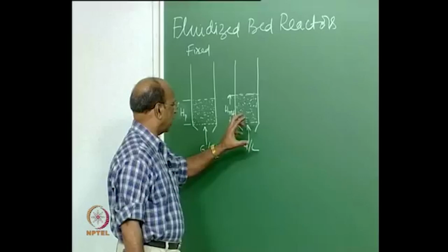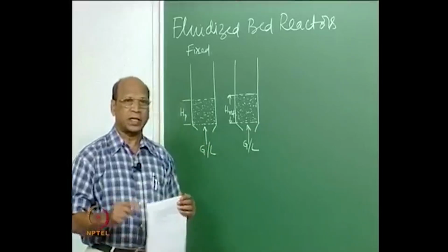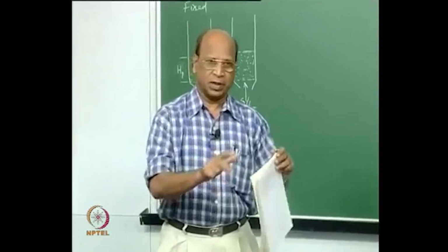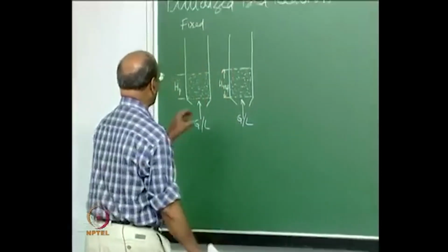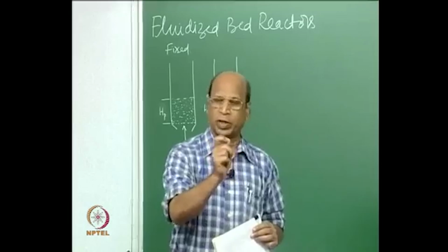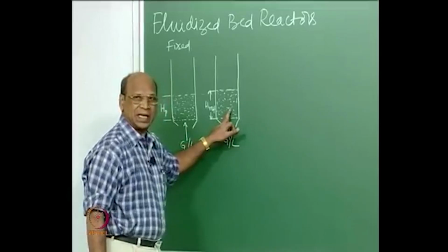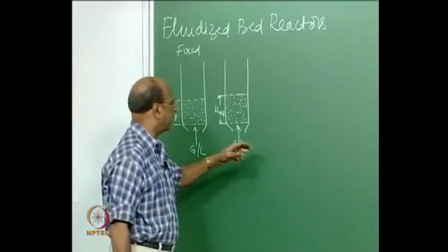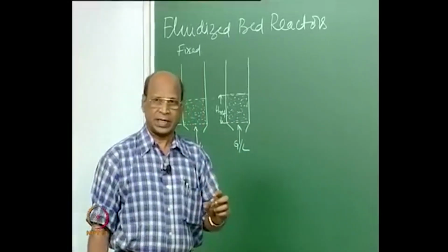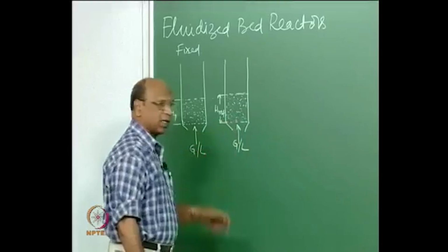little bit, the particles move a little bit, but still the bed is not expanding that much, the particles try to readjust themselves, okay, in a relaxed manner. So, then it will try to move in that restricted place a little bit, like small vibrations, small movement of the solids. So, at minimum fluidization velocity, if you look at the bed, it is not exactly like vigorously moving solids, but definitely solids will readjust themselves, capable of moving even at that time, but not to great distances, and the distance between each particle is also not that much.